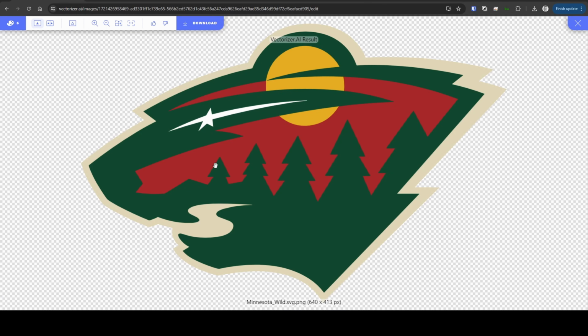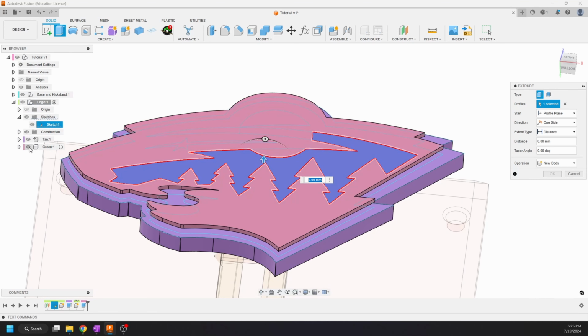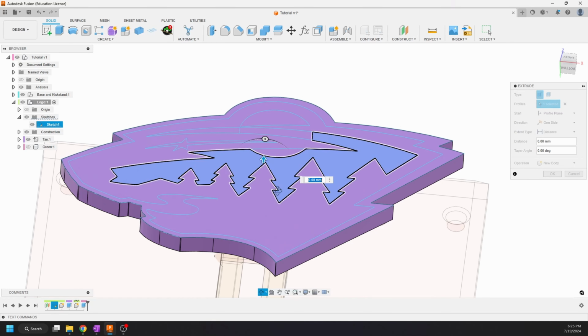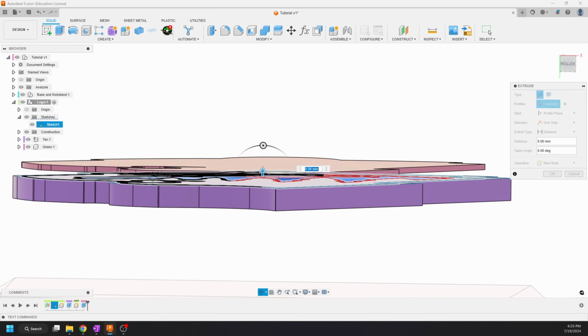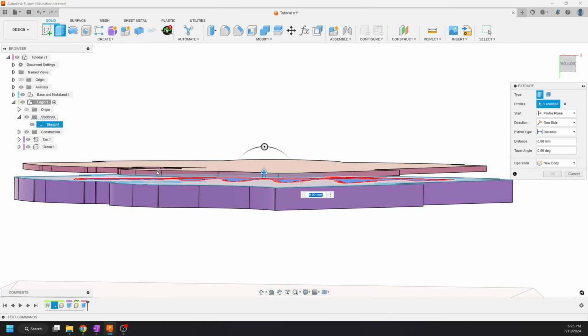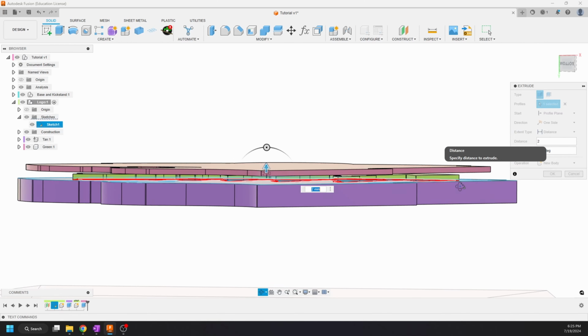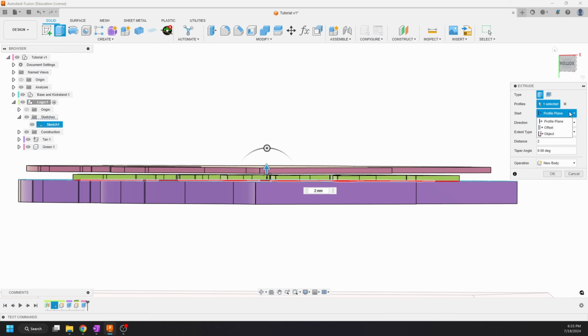and keep in mind, we have already extruded the green, right? So we want to make sure that this red is extruded above the green. Makes sense, right? So the green is extruded 3 millimeters, and then it's 2 millimeters thick. So if I extrude this 5 millimeters at 2 millimeter thickness, it's going to be sitting right on top of this. So for distance, we're going to do 2 millimeters again. That's the thickness that I want it to be at. And offset, let's do 7.